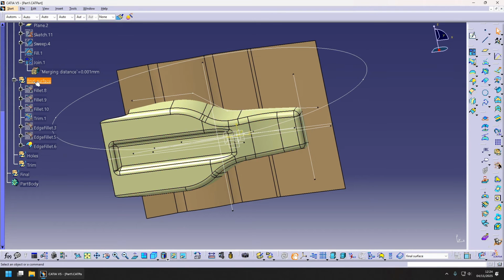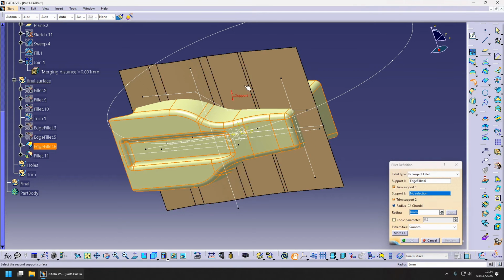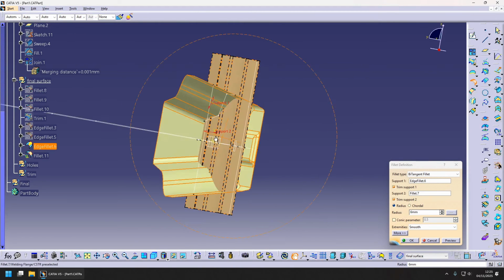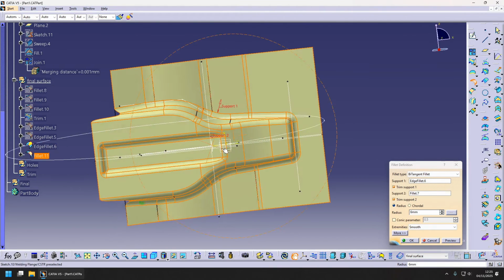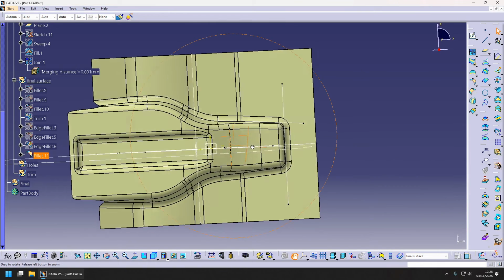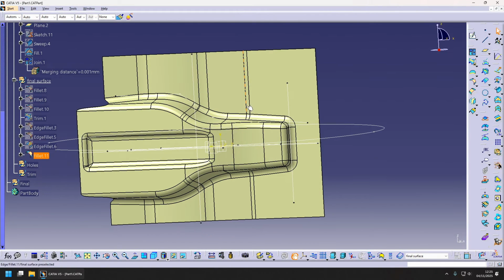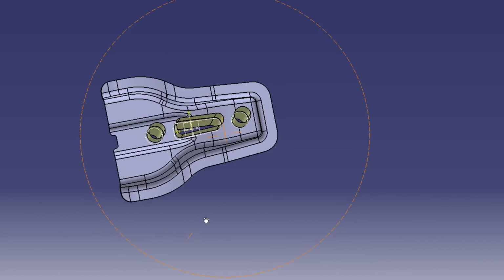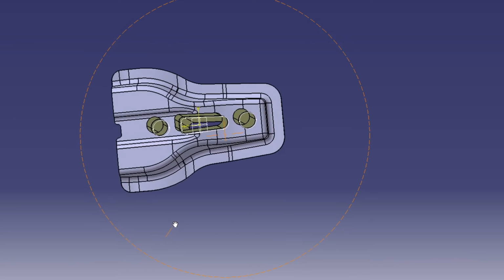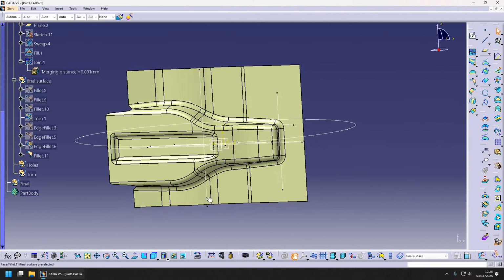Alright, now, since we're in the final part, we're going to add the welding surface to this. And to do that, we just use another fillet. Make sure we have the orientation right. So that is the base surface from which we will cut our part. But to do that, we first need to add our holes. The holes you should always keep separate, as they can change a lot in the part, and these are the ones that you might actually update the most. Let's see how this is gonna work.